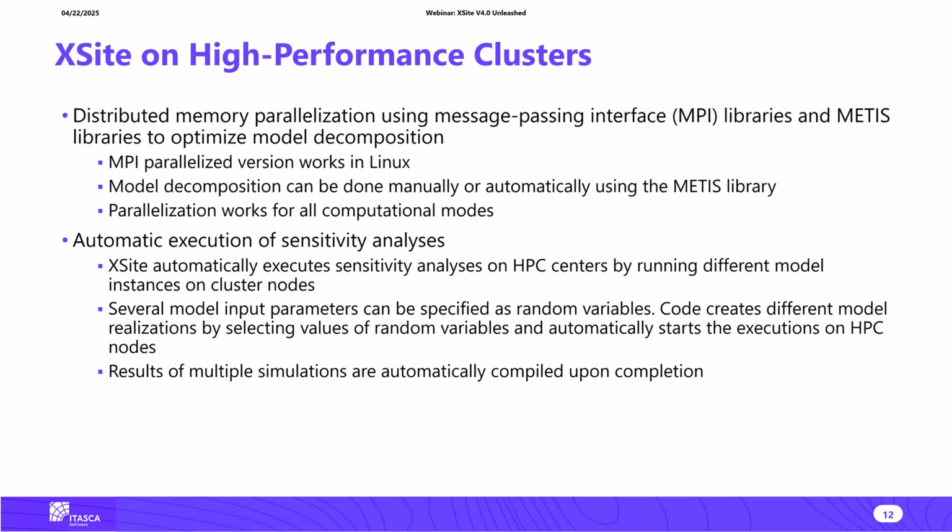An important thing is that when these sensitivity analyses are set up, the user can specify which of the input parameters are uncertain or are provided as statistical variables. For example, the user can specify that in situ stress, Young's modulus, and, let's say, the DFN are uncertain. For Young's modulus, the user can provide the mean value and standard deviation. For the DFN, the user can provide multiple realizations.